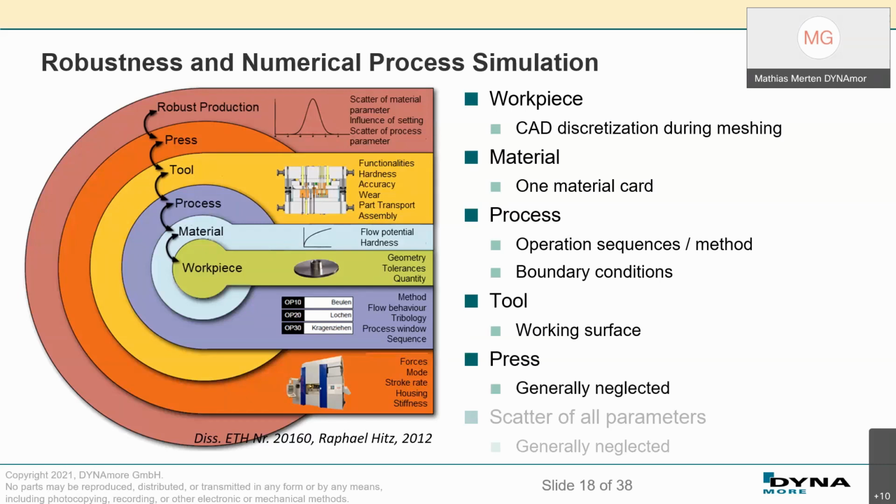What can happen in reality? You produce a tool in, let's say, Germany. You make the tryout in Germany and you ship the tool, for example, to any other country, for example, Poland. And there your plant or your company has a different press. And then you need to do another tryout as the press types are different. And the elastic deflections of the tool surface caused by these different press stiffnesses cause, for example, production with a lot of mistakes or with a lot of rejected parts.